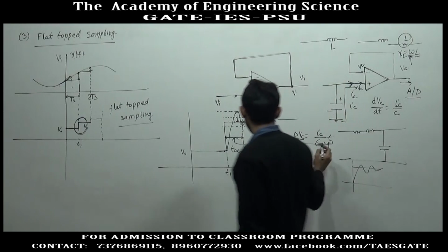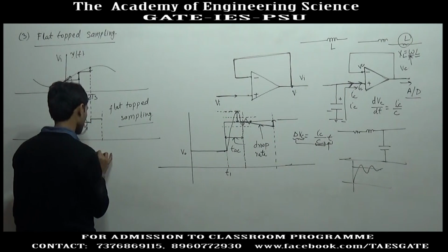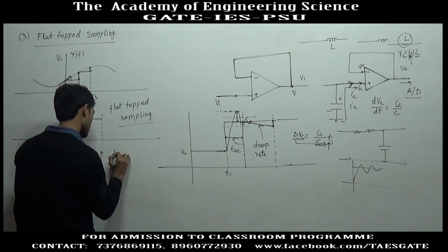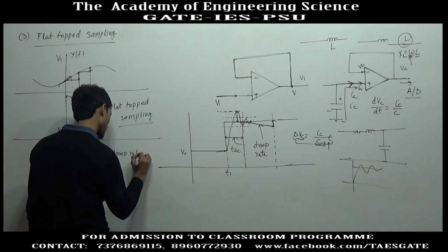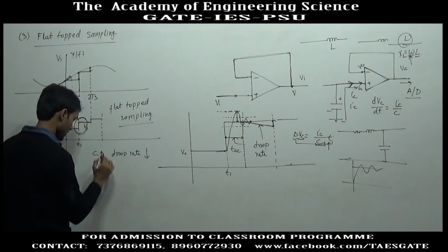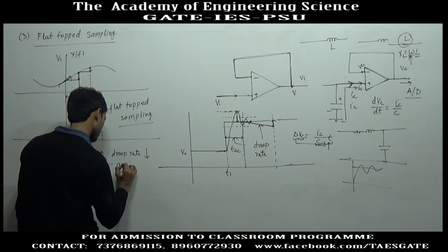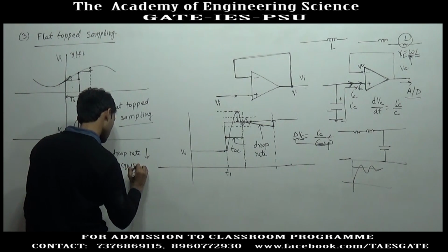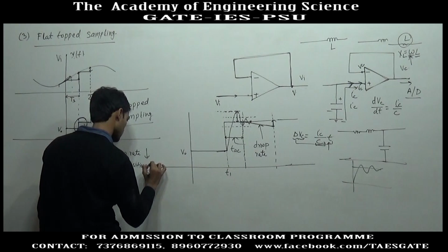If capacitance is increased, droop rate will decrease and acquisition time will increase.